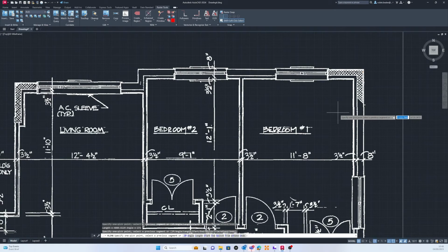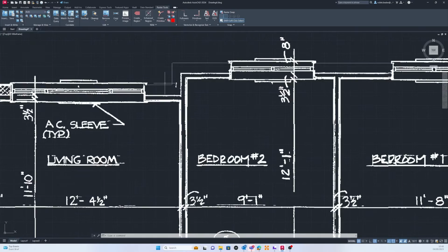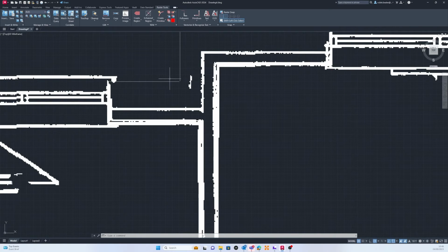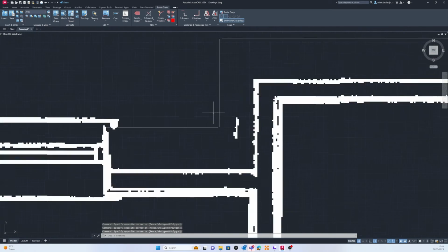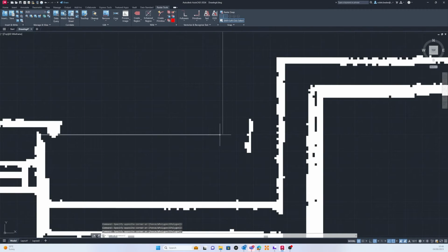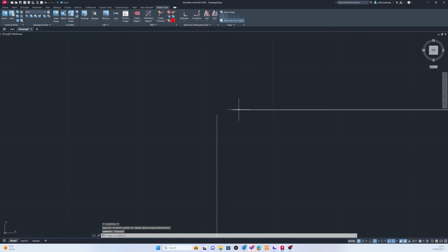And then if I just hit enter a couple of times, you'll notice AutoCAD does something really quite clever, in that it gets rid of the rasterized images wherever we have converted it into AutoCAD geometry. And then naturally from there, we can use trim, or we can use extend, or we can just drag these into place using snapping to get these lines to conform and work where they need to be.